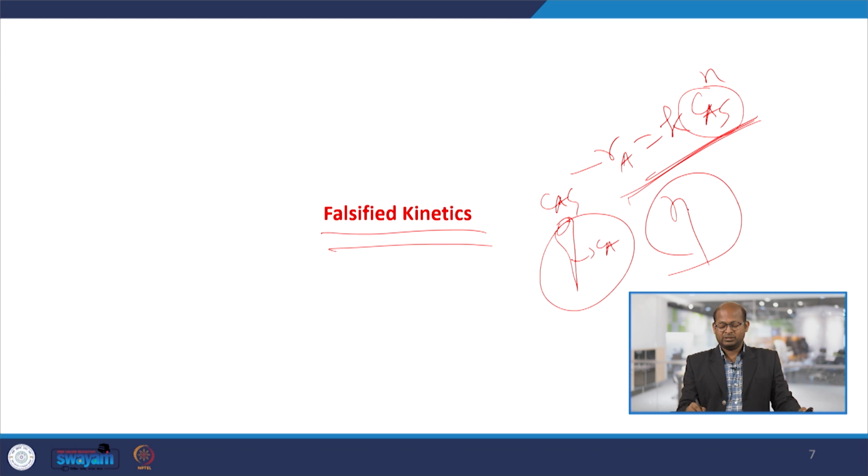Here we usually express the surface concentrations, but when the catalyst is spherical and has pores inside, the concentrations would be different. If the concentration at different locations inside the particle differs from the surface concentration, then the rate would be different from inside to outside. Therefore, the effectiveness factor comes in. If the rates do not differ, the effectiveness factor is 1, so then we can say that there is no diffusion.